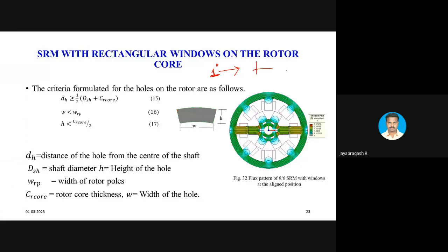For an example, let me tell you. We use pole shoes, right? Generally, the pole shoes are curved like this. The reason for curvature is to distribute the flux evenly in the air gap, so that your alternator can produce a sinusoidal waveform like this. Instead, if I introduce a very small flat region like this, you don't get a sinusoidal waveform, rather you will get a flat topped waveform. It looks like sinusoidal, but it is a highly distorted sinusoidal component. If this is injected into the machine, obviously your machine will produce a lot of torque ripple, leading to acoustic noise and vibration.